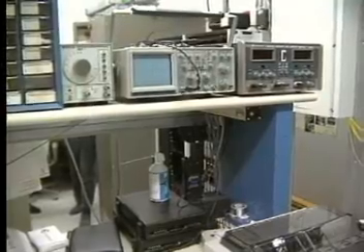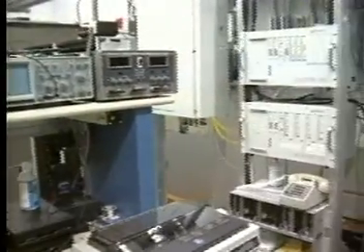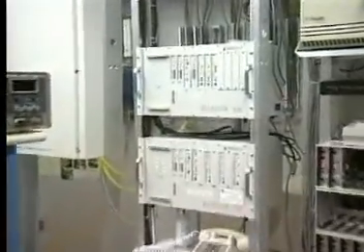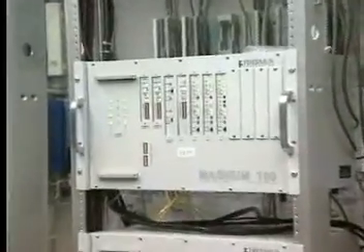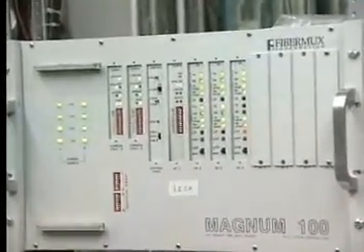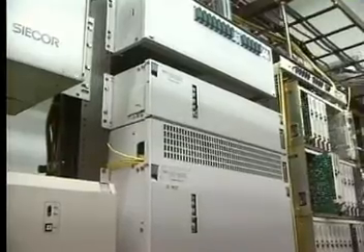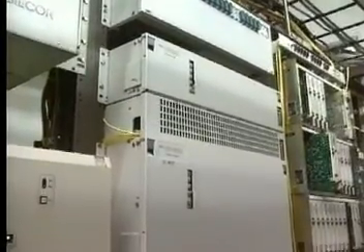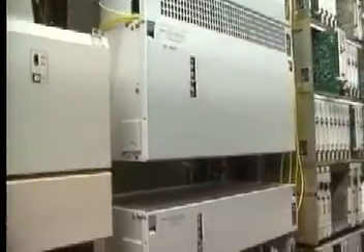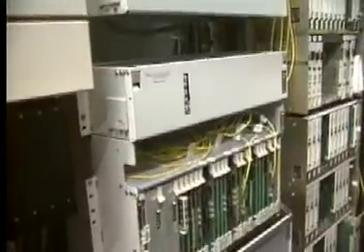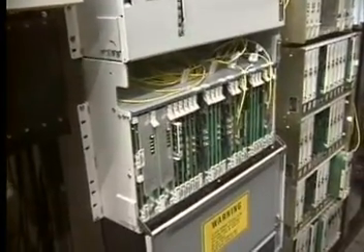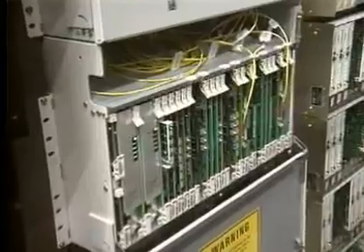The choice between LED or laser will also include total fiber distance, the allowable number of repeaters in the system, as well as cost and reliability factors. The greater power level offered by lasers allows greater distances with fewer repeaters. However, lasers generally cost more than LEDs and have lower mean time between failures.